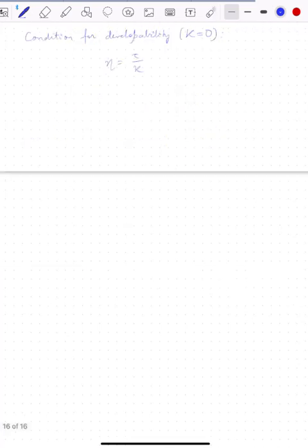So finally, we have the bending energy. And it so happens that bending energy is just a function of one principal curvature. Since the Gaussian curvature is 0, it implies that one of the principal curvatures is 0. So let's only have kappa 1, which is the non-zero one, and then dA, right? And then this can be integrated, so this will vary from 0 to L, and this will be from minus W by 2 to W by 2.